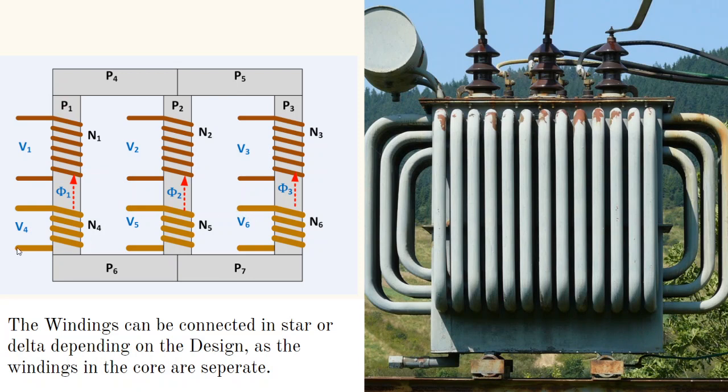So it's all about how you configure it, how you connect it together. You're talking about phase voltages, line voltages, what voltage you require, what currents you require, and what efficiency you're going to be working at. How much power you're going to be transmitting, how many lines of wires or conductors do you require. When I talk about a delta connection, I need 3 wires. When I have a star connection, I have 4 wires. When I generate power to balance it, I have the 4th wire.